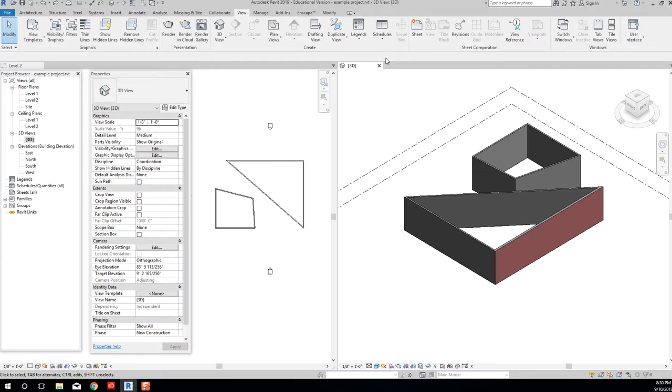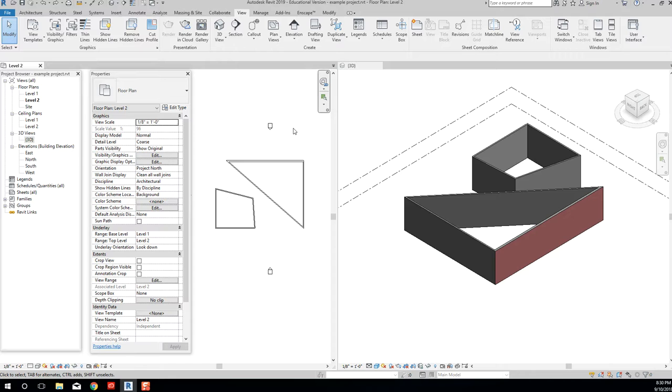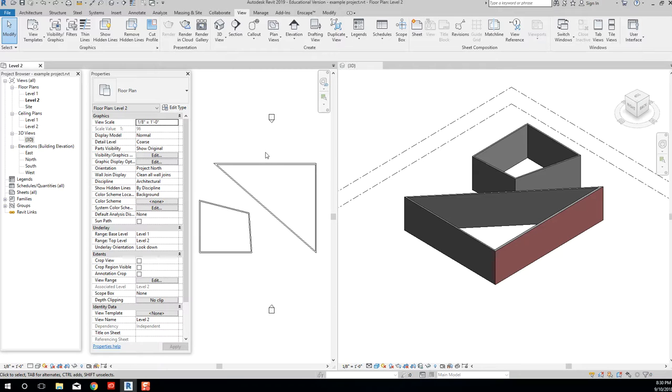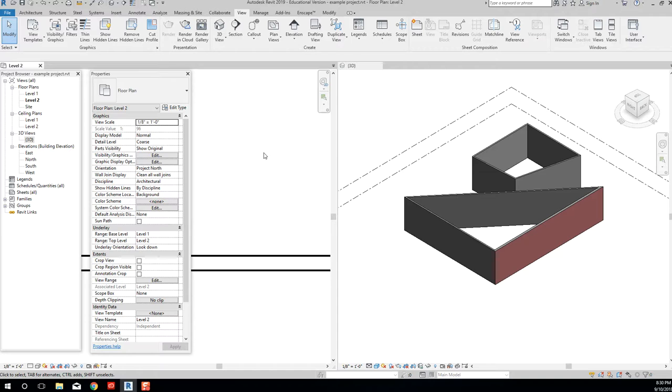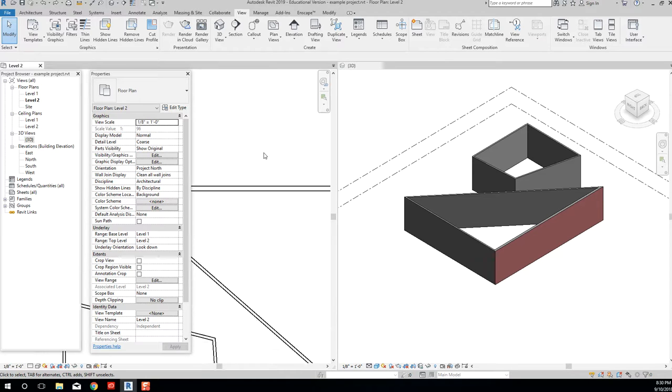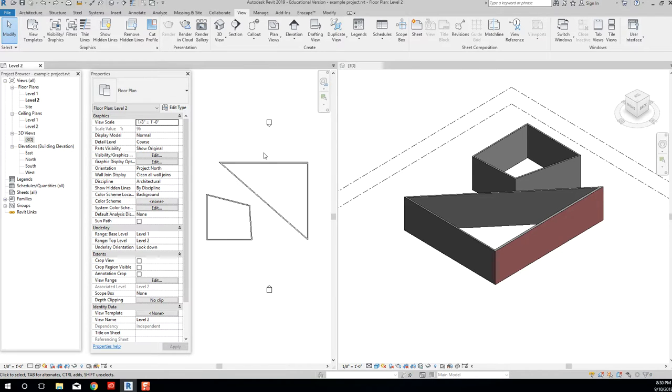All right. So let's talk a little bit about, and again, we talked about this just a little bit, but I just want to make sure everybody's clear on it, navigation in Revit. And the first thing I want to make clear is that we can use our mouse to navigate, okay? So when I'm in a 2D view, like a floor plan or an elevation, I can use my middle roller button and push it towards the screen, away from me, and I zoom in. And I can pull it towards me and I can zoom out, okay?